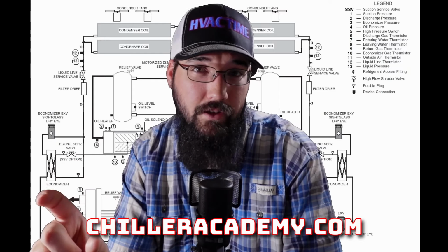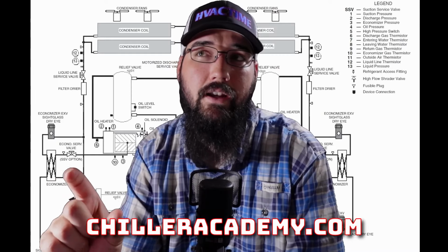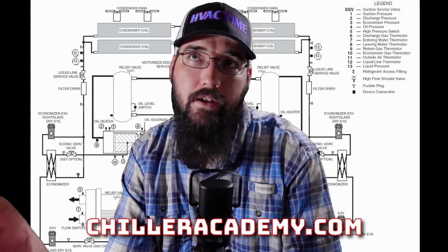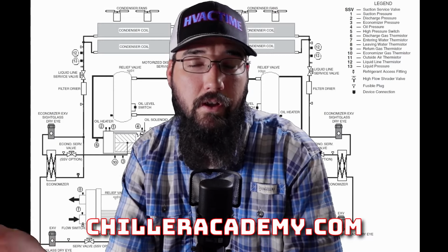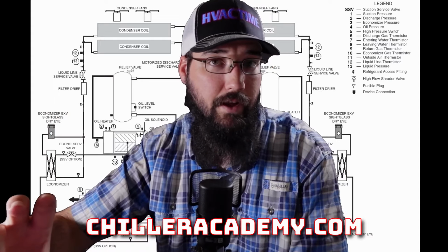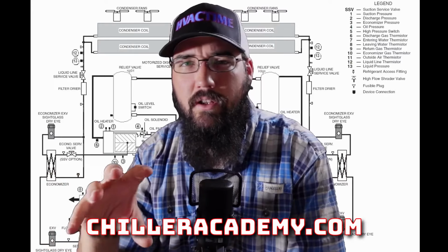That is a weird concept if you've not worked with it previously: we didn't change speed, but because our load changed, our amp draw changed. So now we can load the compressor more, or speed it up more. Because our current draw fell, even though our Hertz remained, we can now increase our Hertz output because we're down below current limit. I really hope this is making sense.